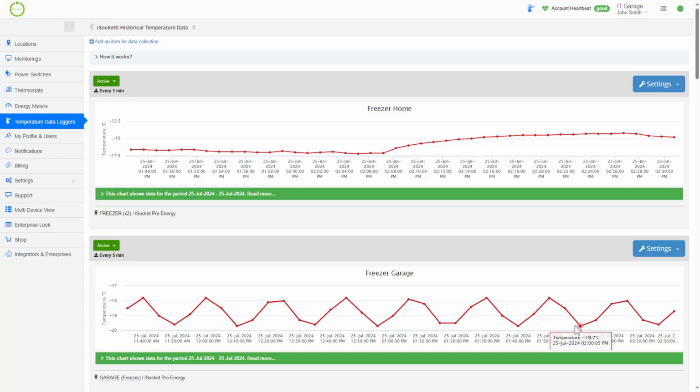Yeah. So when you see, for example, on the door, if you have a digital indicator and it shows you minus 18 all the time, or 0 Fahrenheit, it is not true. They fake information for you as an end user. But when you put this sensor inside, you're monitoring the true temperature without faking. So when the compressor stops, it rises to that temperature.